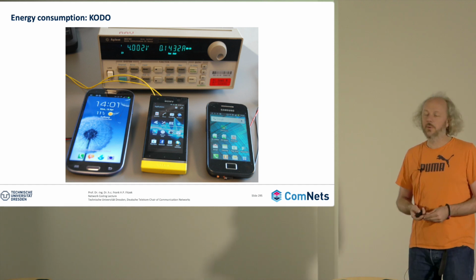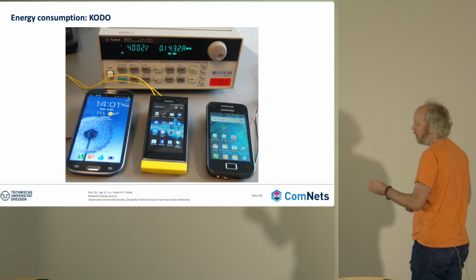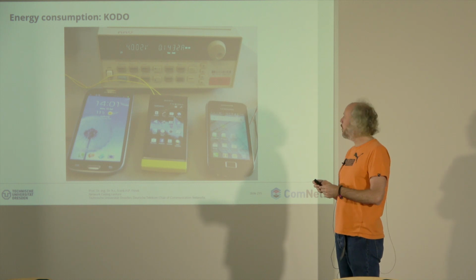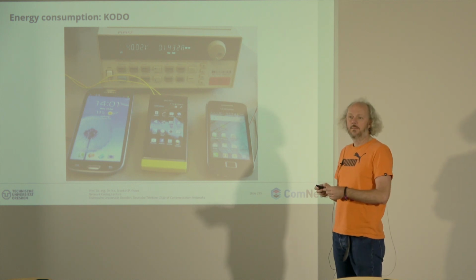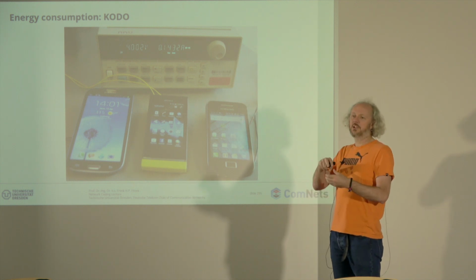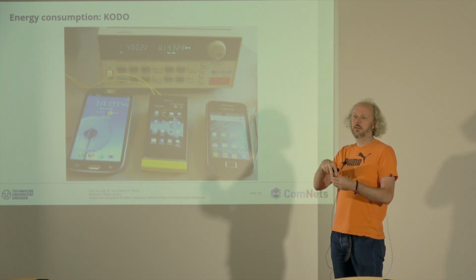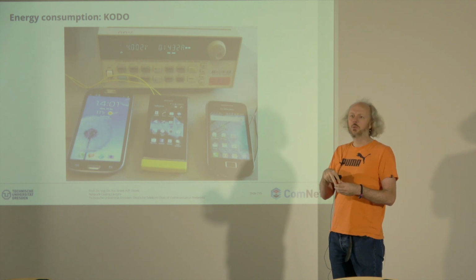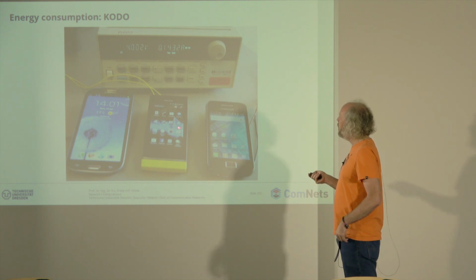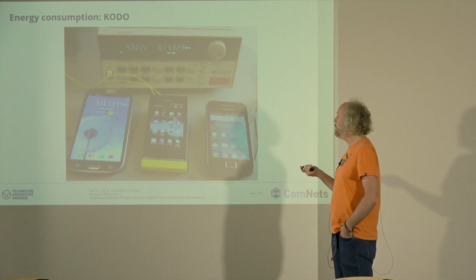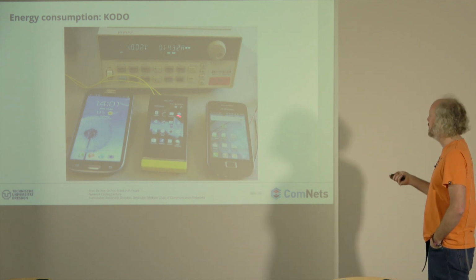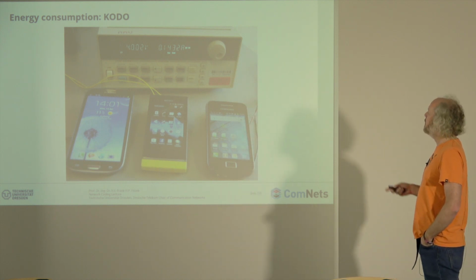You're destroying the phone, which is not really the issue, but getting it out and then taking the battery away, the whole system does not start. This is an issue. So one simple thing is the phone is measuring the inner resistance of the battery. I think it was 82 kilo ohm for the Nokia phones. Others have different values. So they find out if it's really their own. And now there will be chips involved, so you have to find out what the signature of the battery is so that it starts and you can really measure that. But this is only a side note.